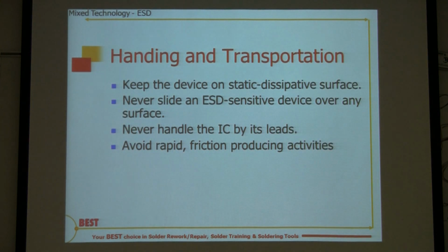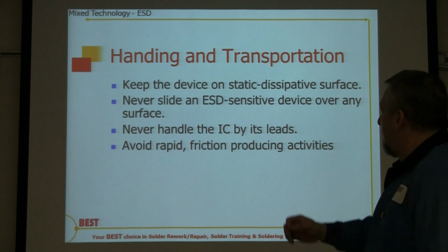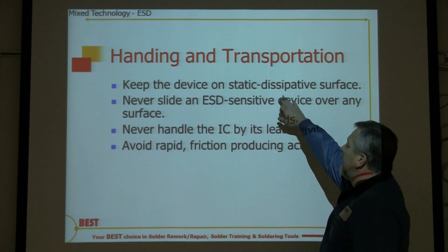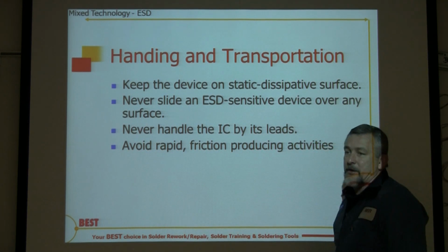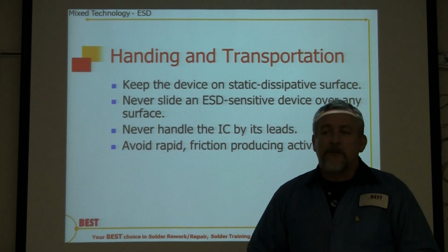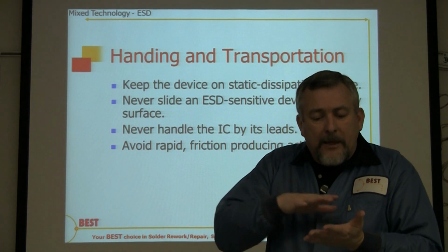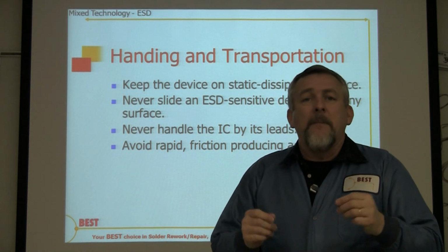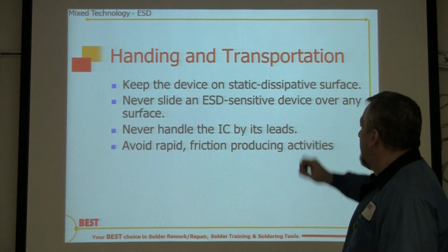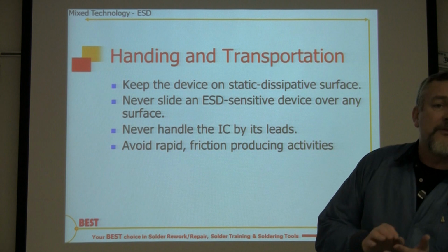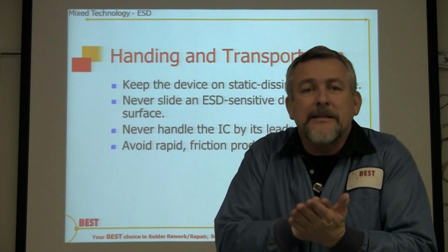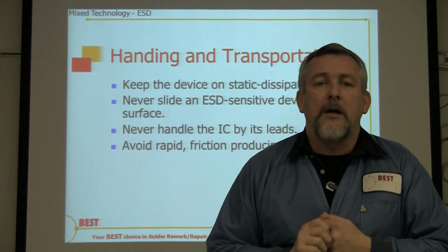Some of the handling and transportation rules. It says here, first off, keep the device on a static dissipative surface. Keep it on that mat until you're ready to put it inside of that bag. Makes it very easy. Keep all leads on there too. Remember, it says never slide an ESD sensitive device over any surface. Remember, sliding causes static electricity, and we don't want to cause that.